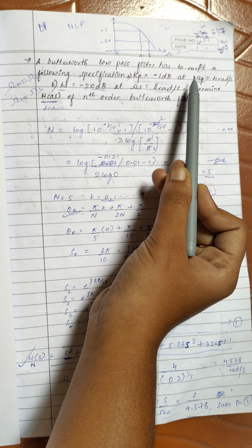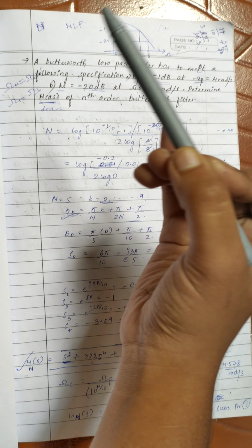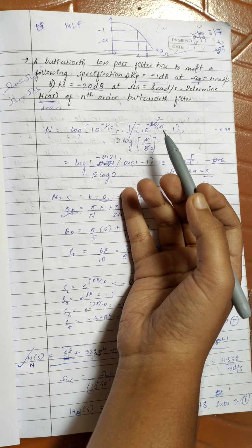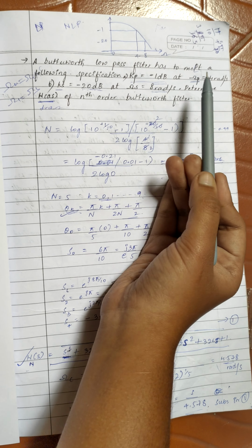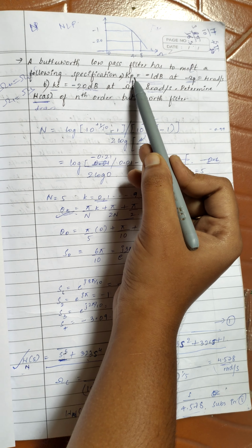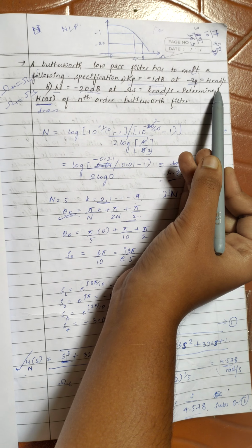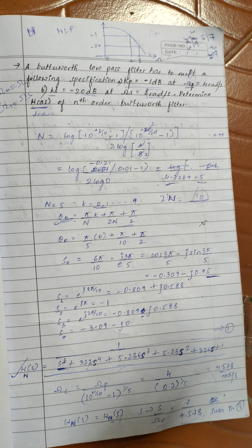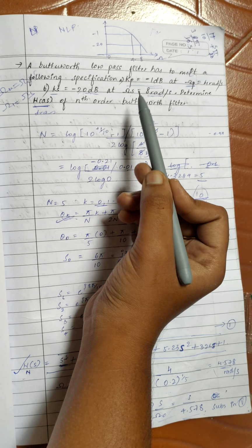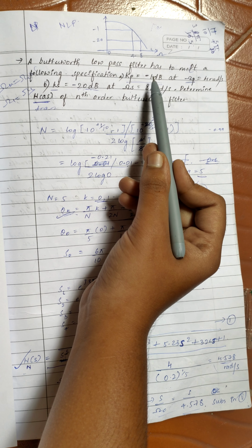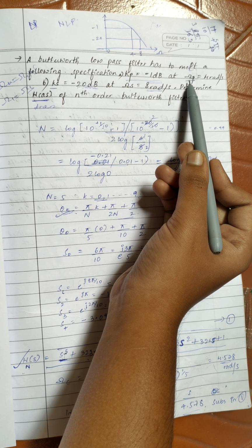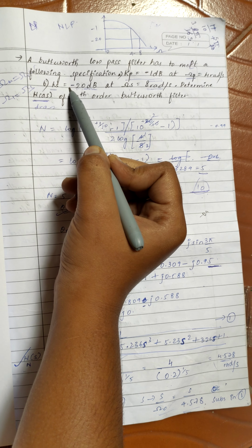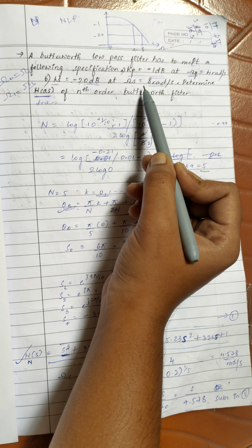See, actually they have given normalized low pass filter values. We have to find the analog low pass filter from it. Okay, so how do we do that is what we require. Actually, this Kp, omega p and all, they will give as passband attenuation, passband frequency, stop band attenuation and stop band frequency. Don't get confused if they give such terms in the question. Passband attenuation or passband gain is nothing but your Kp. Passband frequency is omega p. Stop band attenuation or gain is Ks and stop band frequency is omega s.